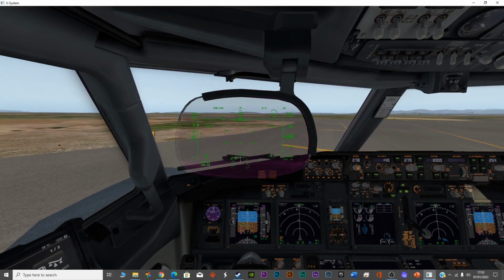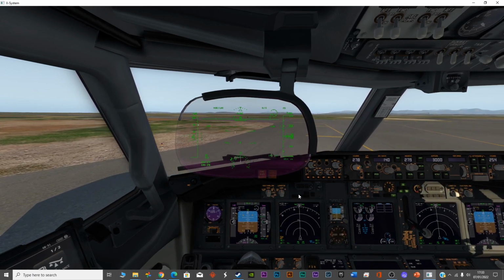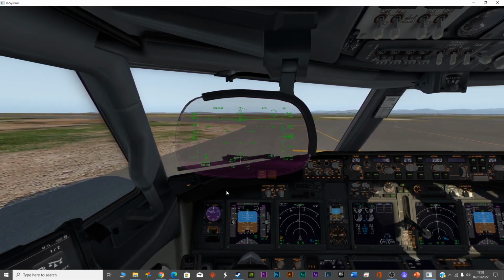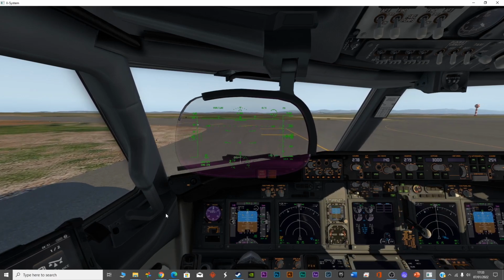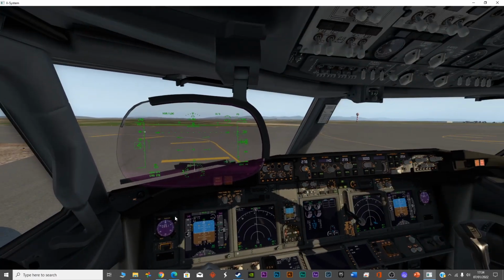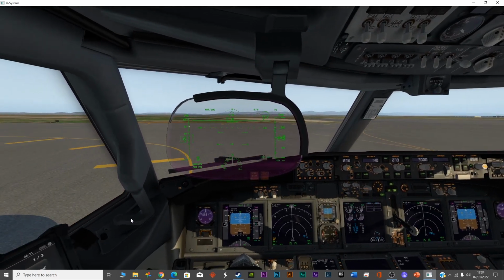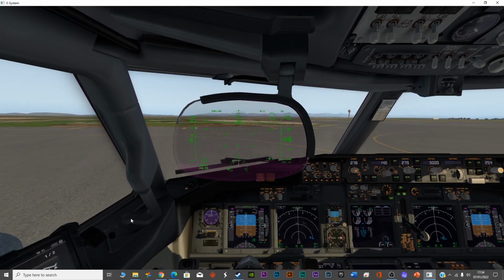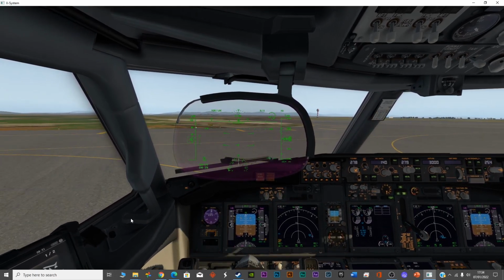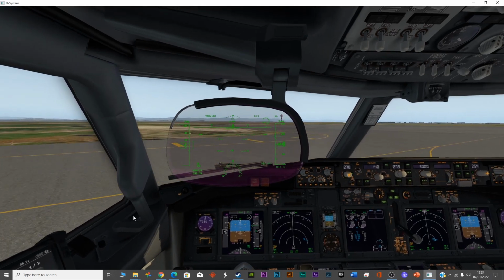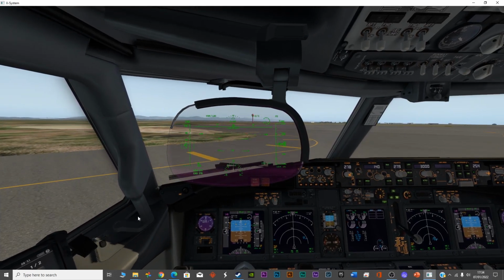And hopefully, you see, because I started the plane again from the runway, the wheel axis was not set to yaw. That's why you can see I'm having difficulty in turning this plane. So just remember to activate this option. You see, it's taking a bigger round for the turn.